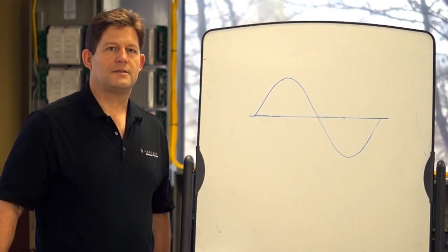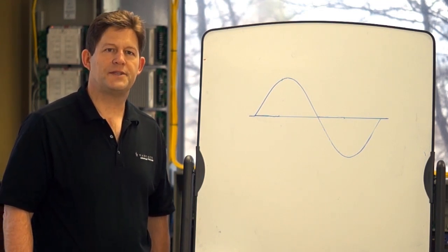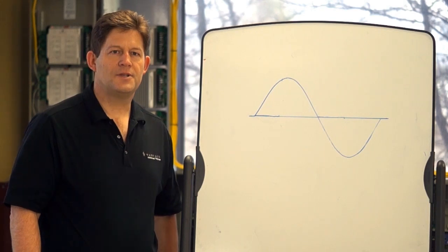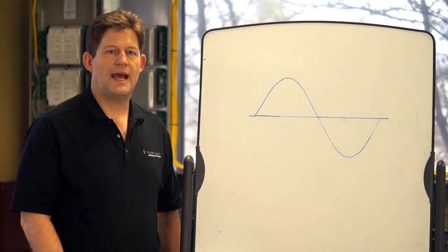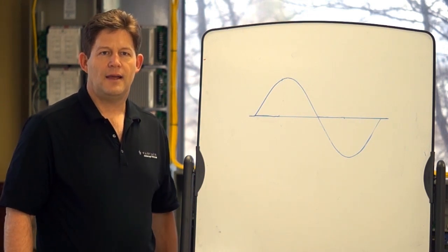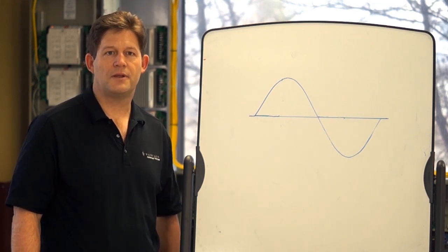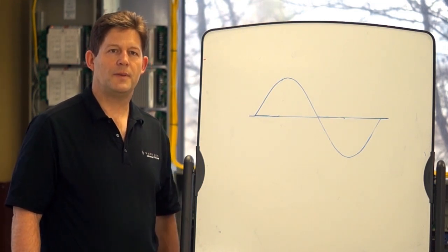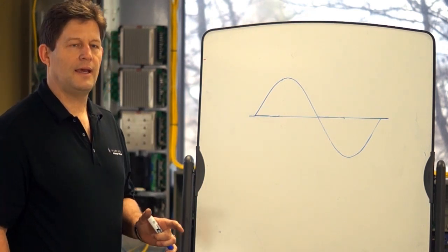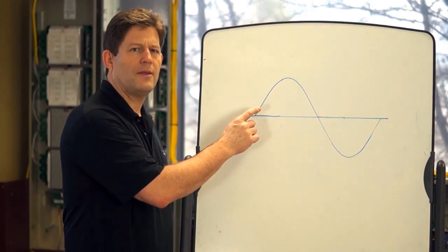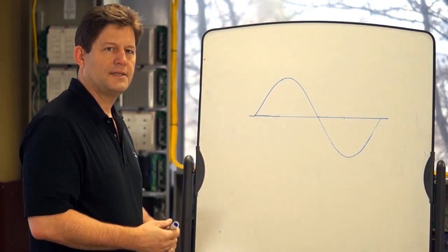This graphic represents a single cycle of the delivered sinusoidal voltage signal. This cycle repeats 60 times every second. Using a simple light switch and turning that switch on, we would be delivering this voltage to the lighting load throughout the entire cycle. As a result, current would flow through the lighting load. The product of the voltage applied and the resulting current through the lighting load would determine the power delivered to the lighting load. To reduce the light level output again, we need to reduce the amount of power that's delivered, and we'll do so by switching twice, off and on, during each cycle.